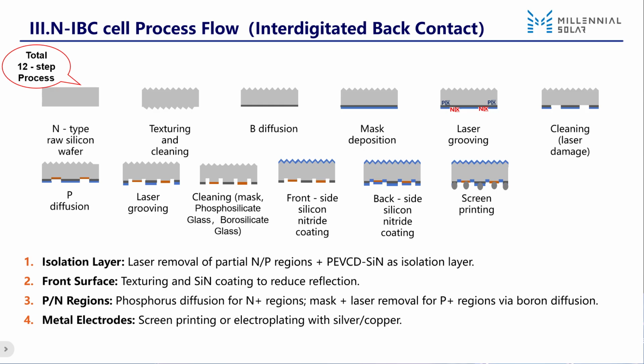What's the purpose of this cleaning? There are mainly 3 points. First, when cutting the silicon rod into wafers, it causes surface damage. So, the first step is to remove this damage because these damaged areas are defects that can capture carriers. Second, we need to form a textured surface to reduce reflectivity and enhance light absorption. Third, we need to remove oil stains and metal impurities on the surface. These are the main purposes.